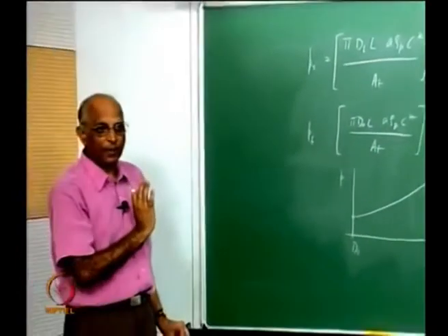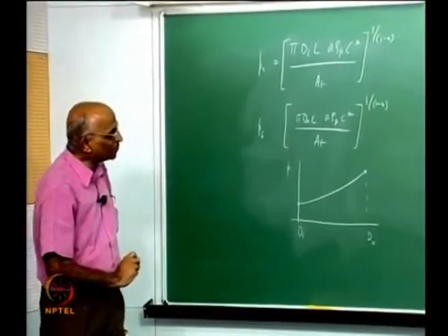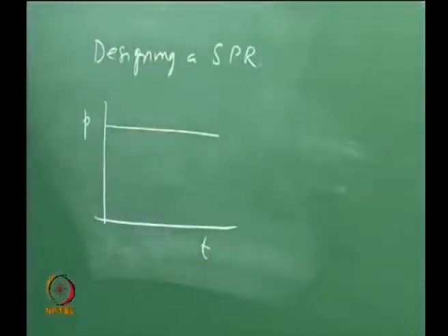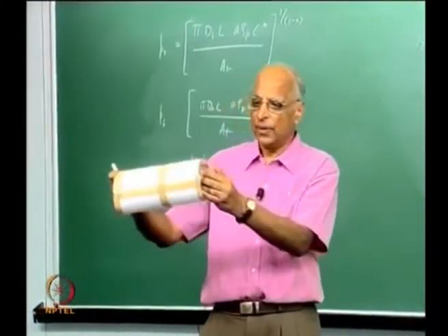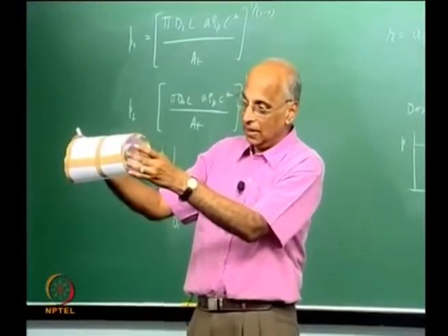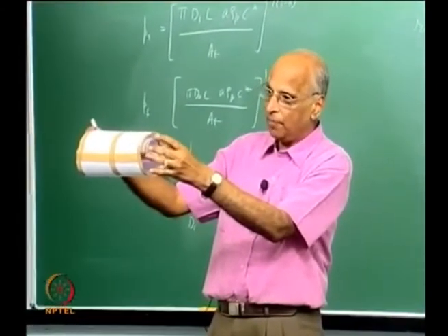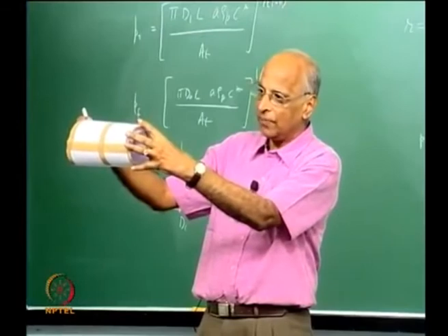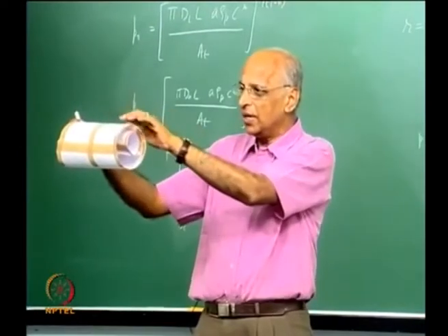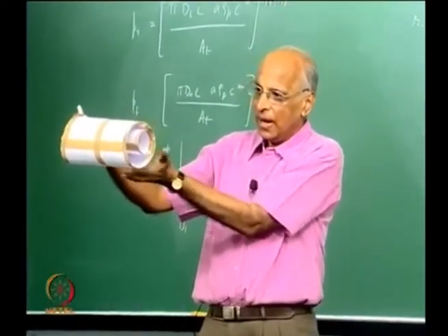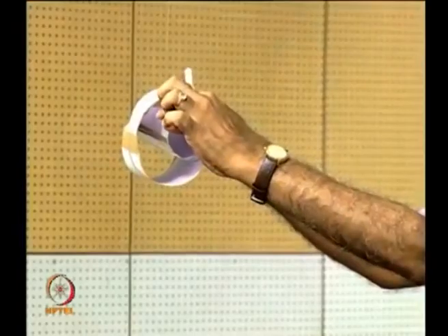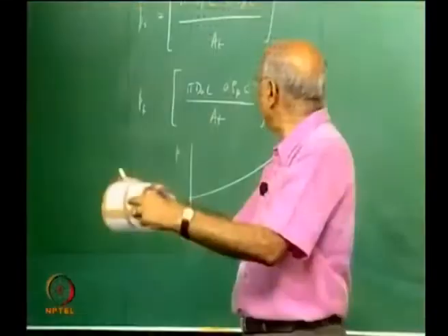Is this all right? If this is all right, now I will ask myself one last question. If instead of having the grain start burning at the inner diameter and progressively burn to the outer diameter, I somehow put the case over here, I ignite the outer surface and then the flame propagates inward, then what is going to happen to me?